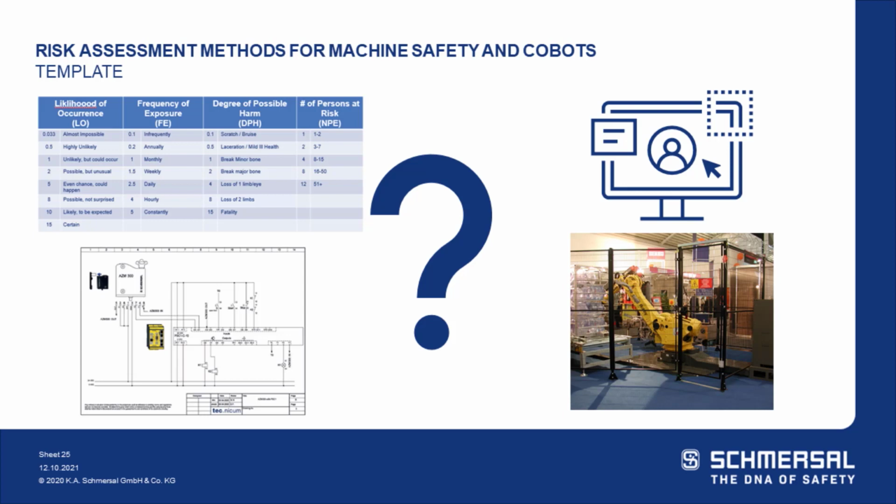So we think a great method to start is, first, determine the quantifiable method you want to use for the risk assessments. Again, we showed the HRN method. Second, determine the Type C standards you use in your facility. So find the machines that you use that have Type C standards. From there, you can build a spreadsheet or buy software, and introduce your quantifiable method and add the sections to answer those Type C questions in the machine-based section of your risk assessment, right?